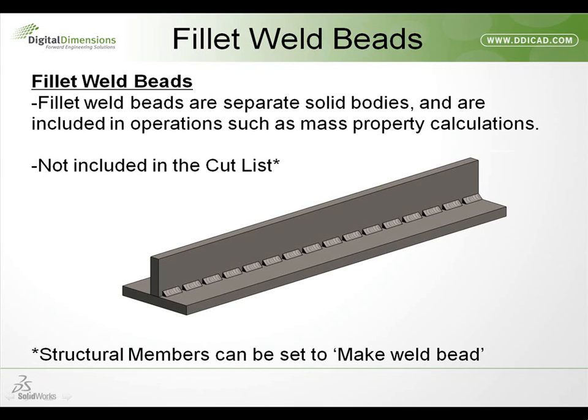To do this, you simply right-click on the structural member in the graphics display and toggle the Make Weld Bead, or to turn it back into a structural member, right-click Make Non-Weld Bead. And with that, I'll show this.